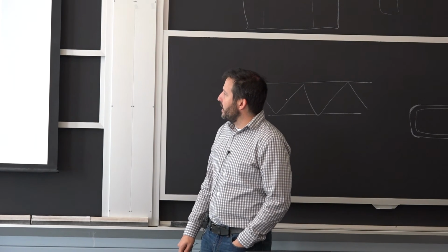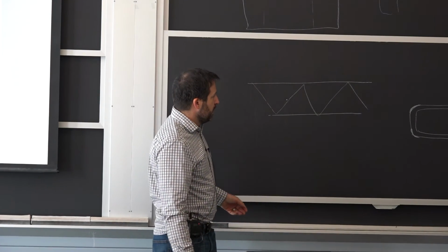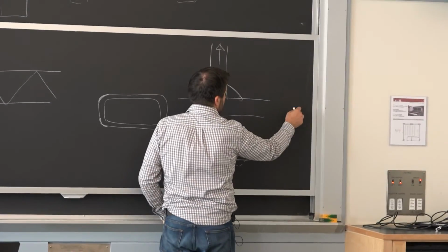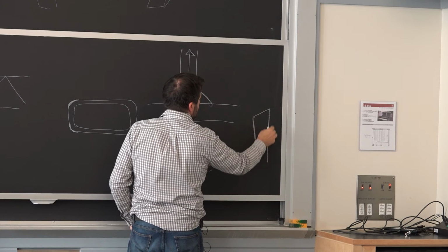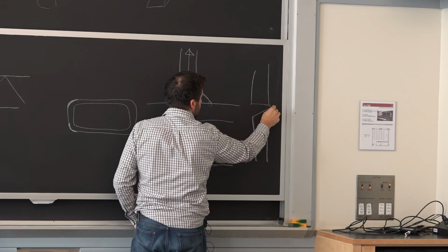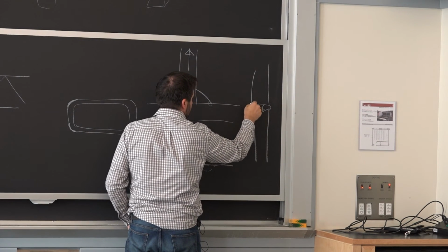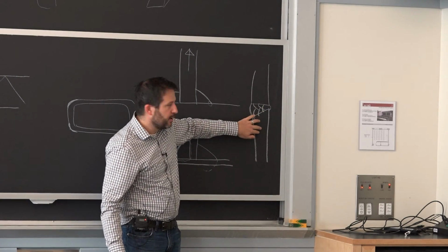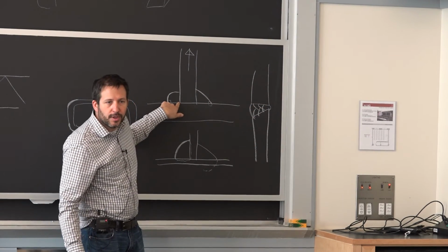So there are ways where you get a better allowable. One of them is here, instead of having this fillet weld, let's say that I make a connection between two plates. One is tapered like this, and the other is straight. And I build up that weld. So that would be the case of a pipeline. And let's say I do it just from the outside, so I've got a number of passes. Well, over here, when you're all done, you have continuity. There's not really a little bit of a corner here.